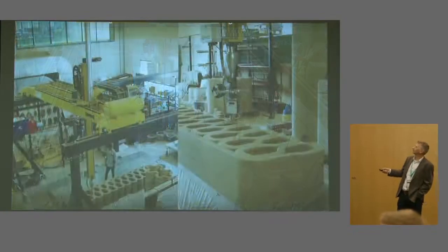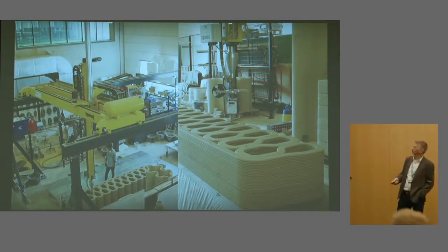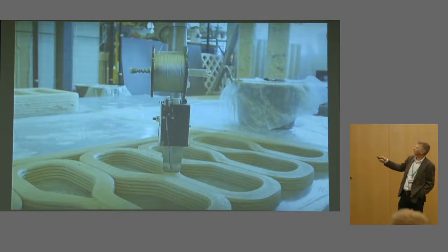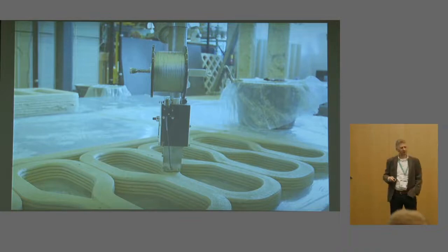And then we printed elements. And we printed the elements just for a height like that because our lift capacity in the laboratory is limited. Otherwise, we could have printed 2 meter high elements. And as you can see, the wiring system is embedded there. So every layer is embedded. So if I pre-stress in the vertical direction here, if I pre-stress the bridge, I know at least there's a wire as a kind of a stirrup acting around for reasons of confinement.